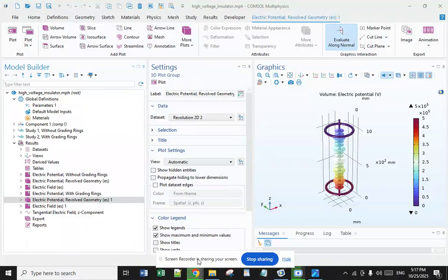What are the main characteristics of high voltage insulator? The main characteristics of high voltage insulators include dielectric and mechanical strength, resistance to contamination, thermal stability, electrical insulation, durability, and ease of installation and maintenance. What design considerations are important for high voltage insulator? Some important design considerations for high voltage insulators include creepage distance, minimum bend radius, insulator surface design, and insulation materials.